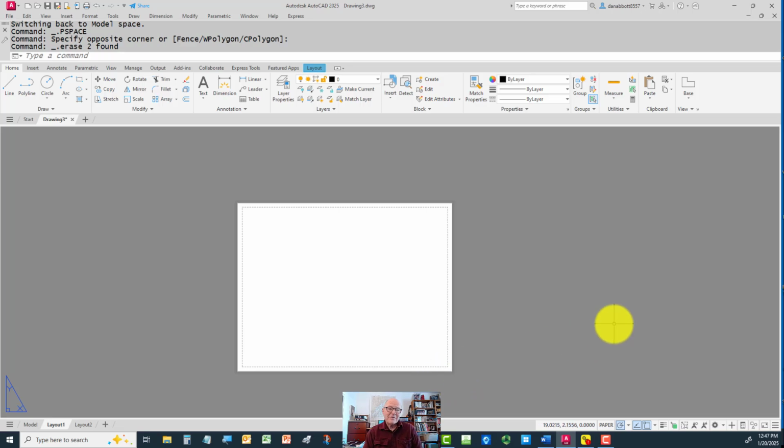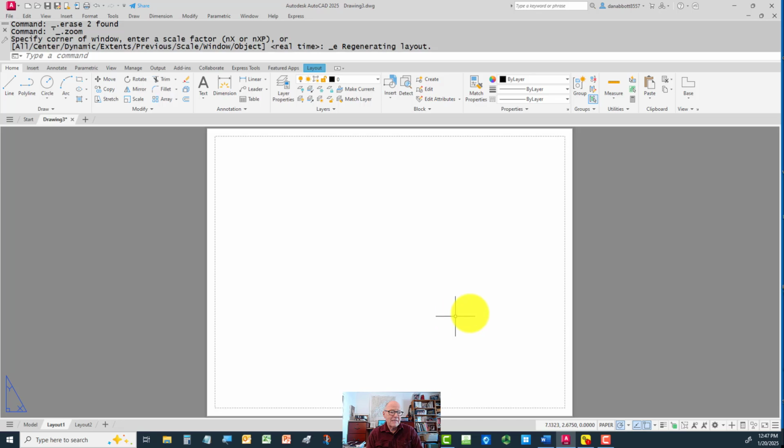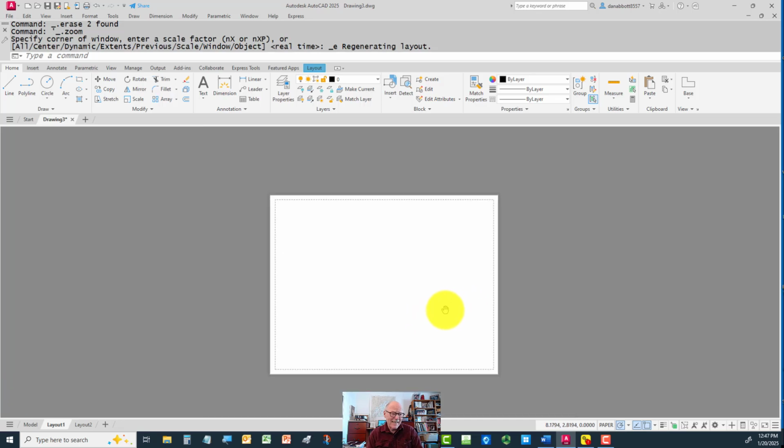So that takes care of text styles, it takes care of dimension style. You know how to put layers in, so I would put the layers in as well. I'll show you a couple of other things I would do just from an interface point of view. But the other thing, and this is something that people disagree about, in fact, my colleague Paul doesn't like this idea. He and I disagree with it. He does not want title blocks to be in a layout in your template file, because that's what I'm doing right now, creating my template file. I think it makes sense to put them there.